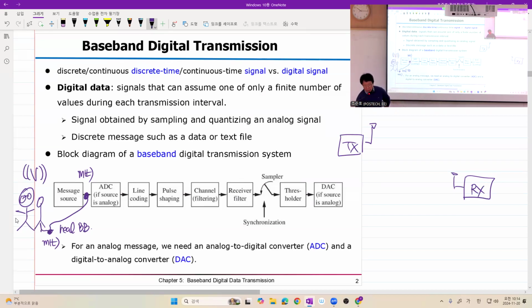Even though they are not located far away, interestingly, if the input to your transmit antenna is around 1 watt, then at just 20 meters, the output at your receive antenna will be a 40 dB to 50 dB decreased signal. What does that mean? This means 10 to the negative 4, and this means 10 to the negative 5.